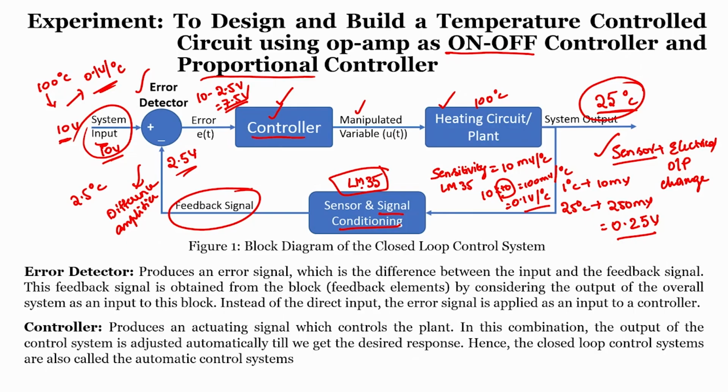That call will be taken by the controller, but that requires some kind of user input. It depends upon what controller you are using. That user input is nothing but the tuning parameters. So, how fast to reach, how much time I require to settle down, right. What is the overshoot that we are getting, whether such a high amount of current is okay to pass through the system in order to have a quick response, a quick ramp to the desired set input, is it okay for the plant or not. Everything will be decided by the tuning parameters of the controller, right.